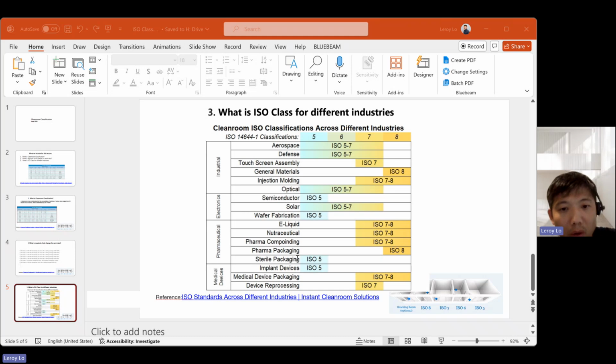But in the semiconductor fabrication industry, they normally design ISO 4, sometimes ISO 3, based on their use and requirements. They obviously want to figure out the most cost-effective mechanical system to reach those levels. Not everything requires the highest level, which is ISO 1.